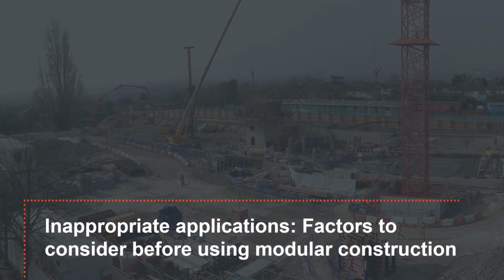While modular has many benefits, it is not a one-size-fits-all solution, and there are several important factors that need to be considered when evaluating whether to use modular construction. These factors include site restrictions. Considering the large sizes possible for some prefabricated construction modules, some measuring up to 2.9 metres by 4.5 metres by 18.75 metres, narrow entries or limited clearance heights for cranes can restrict the delivery of a modular construction solution.